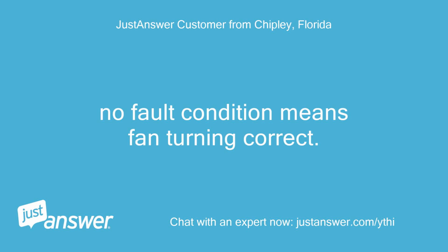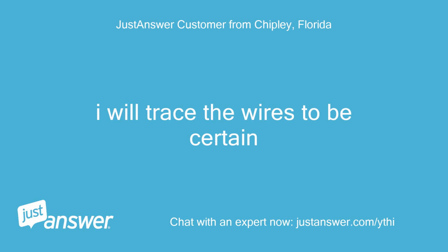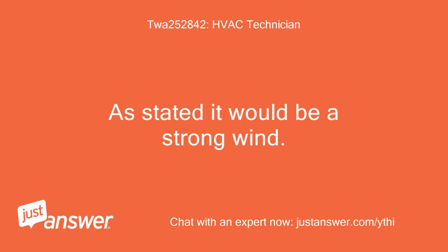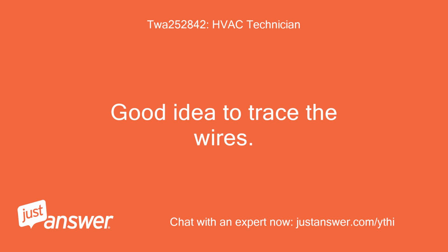No fault condition means fan turning correct. I'm standing at the condenser unit and no external wind blowing. I will trace the wires to be certain. As stated, it would be a strong wind. A breeze usually won't cause the problem. Good idea to trace the wires.